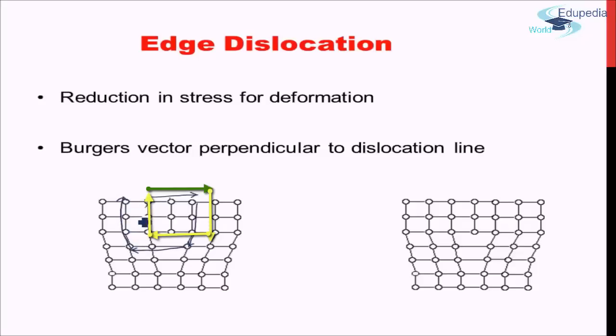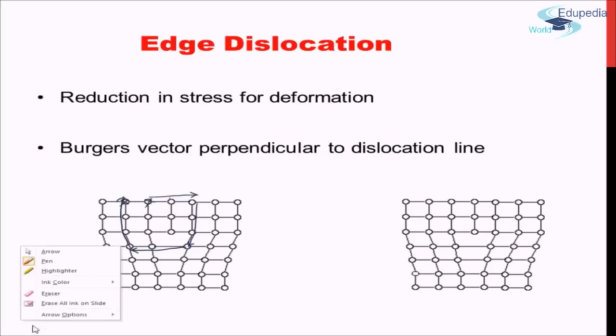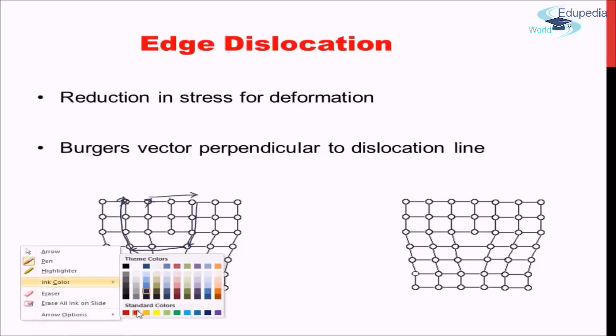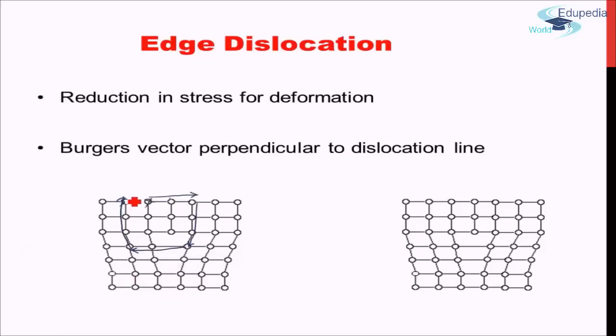Okay. Now what we see is, by going the same number of steps in anti-parallel directions, we have a mismatch. We started from here but we finish over here. Okay, so this mismatch from the finish to the starting point, this vector that we get, is known as the Burgers vector, denoted by B. So the Burgers vector for this dislocation is B over here.